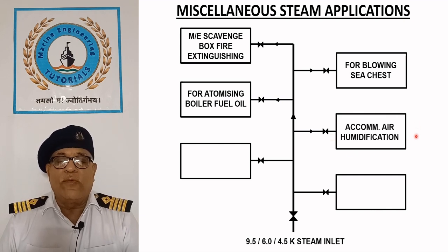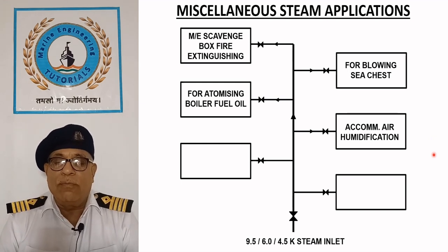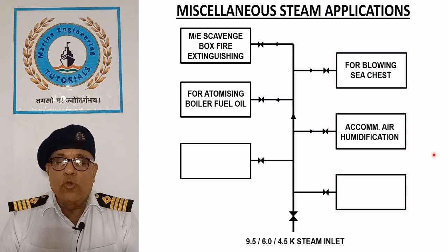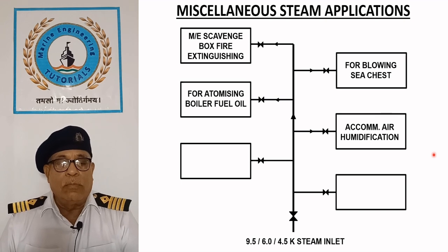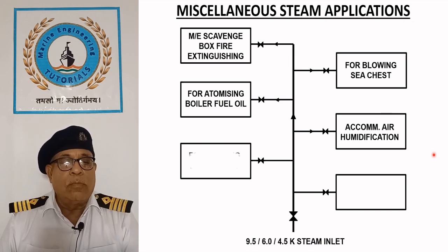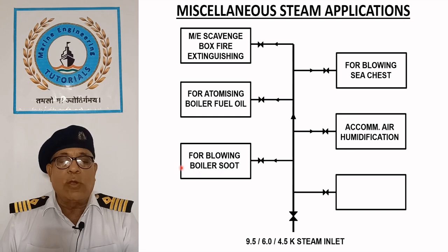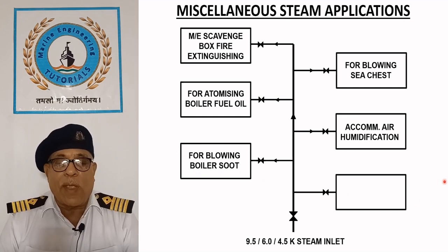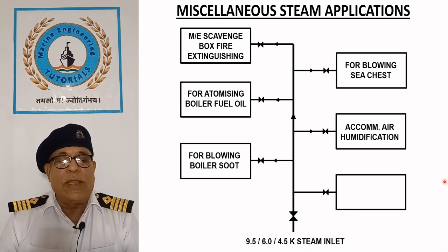Accommodation air humidification. The ship's air conditioning system may be equipped with a steam injection arrangement to humidify the air during winter. For blowing boiler soot. Large boilers and exhaust gas economizers on motor ships are fitted with soot blowers that use steam to keep heating surfaces clean.